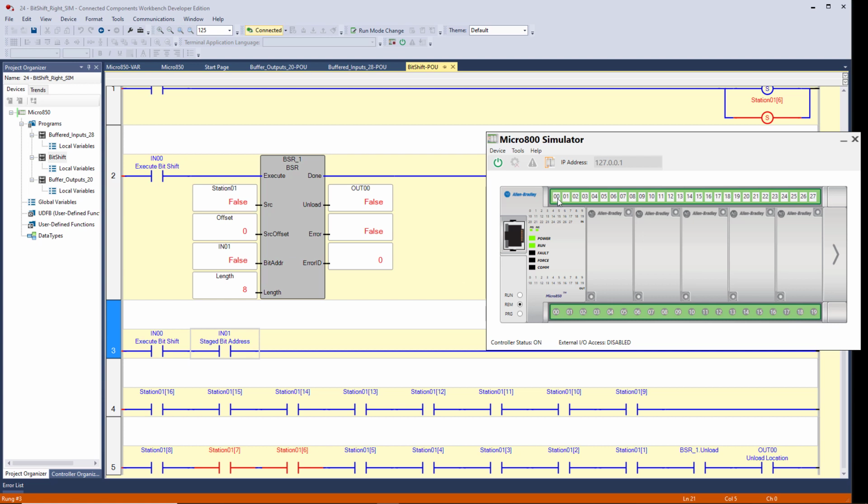And this is going to do this all the way down the trail. Now, if I happen to turn on input 1 somewhere in there, shift it, turn input 1 back off, now I have another bit in here. And as I keep shifting, you see that pattern, that bit pattern of those length of 8 bits keep shifting to the right every time I go on and off with 0.